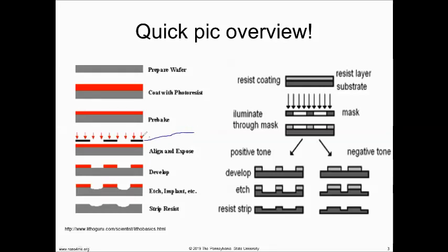Does everybody see? This is my mask right here. I'm circling it in blue. That's a piece of quartz, usually with chrome that blocks light, and where the chrome's not, the light will go through the quartz. Does that make sense? So that's my mask, my permanent mask. But also when I do this part down here, which is very confusing, this becomes my temporary mask, my photoresist pattern transfer. They refer to that as a mask once it's on the wafer. Does that make sense?